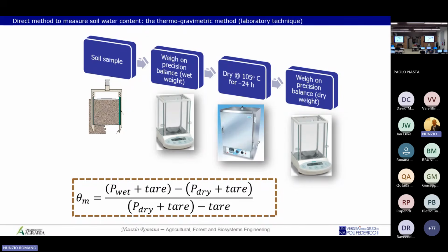Soil hydrology is interested in the movement of water from soil to the root, into the vegetation and toward the atmosphere. So this is the basic. There is not a real strict definition of free water, but mostly I can say water that can move relatively easily into the pore, and then you can compute the water content, the matric potential, and then you move water from one part of the system to another.